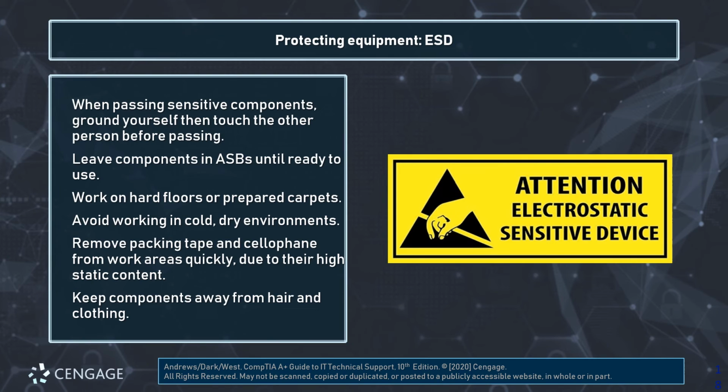You also want to make sure that these components are kept away from hair and clothing. So I don't recommend that you wear a blousy sweater or anything that's really loose or might drag across components. If you have long hair, again, make sure it's tied back. Don't try and balance a video card on your head or anything like that. You want to make sure that any potentially high static environment is minimized as much as possible.